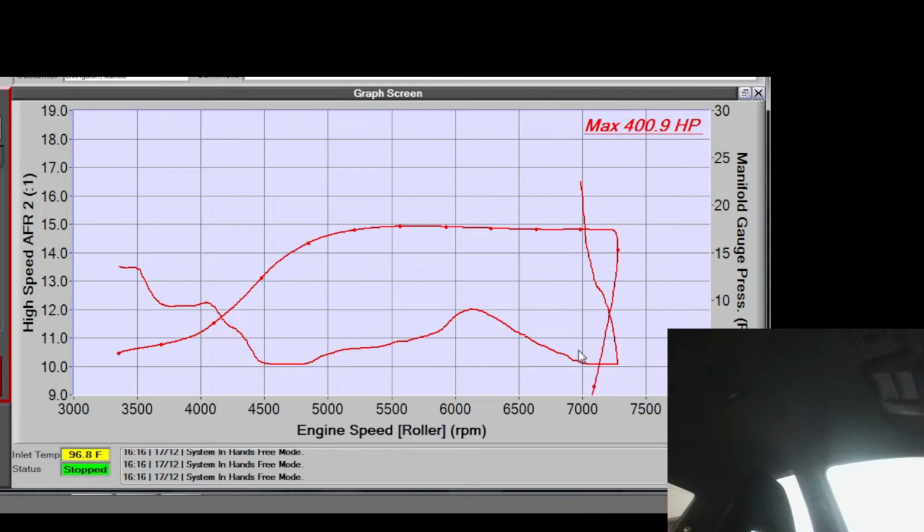Oh, I called it. It does have the old dampers. Oh, wow. I called it. It does have the old dampers. I'll be damned. We gotta take the dampers out of these rails. This fuel pulse dampers, they gotta come out. The old school IAG ones.